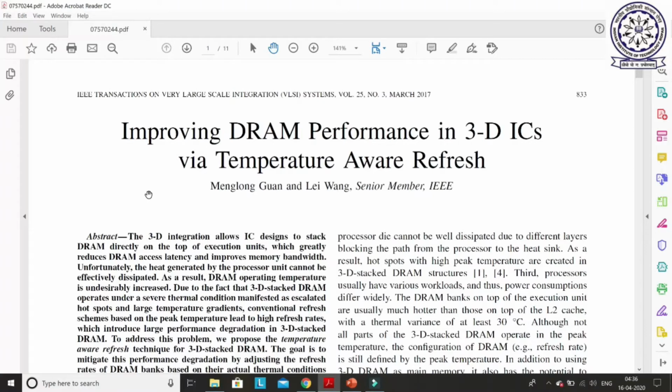The most important point, or a point which is new for this lecture, is DRAM LLC. So till now we know that the last level caches are designed with SRAM, right? And maybe before midsem, when I was discussing non-volatile memories, I explained that non-volatile memories like STT-RAM can also be used to design last level cache. But it is also possible to design last level cache using DRAM technologies.